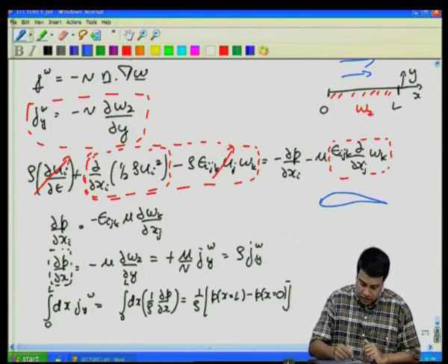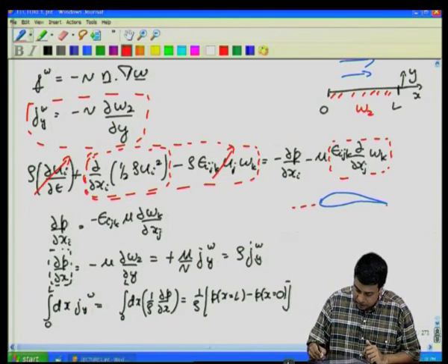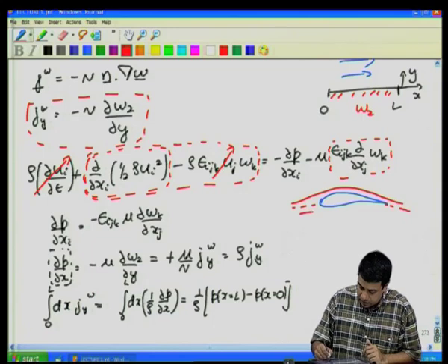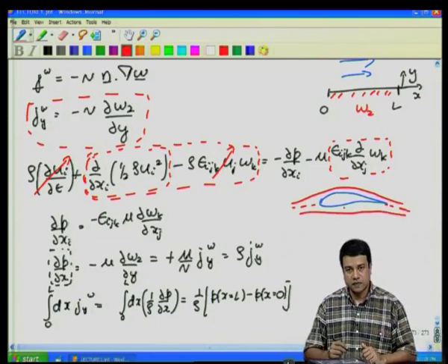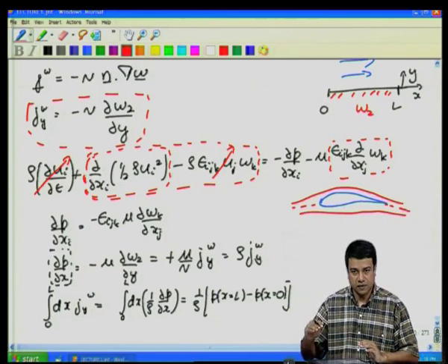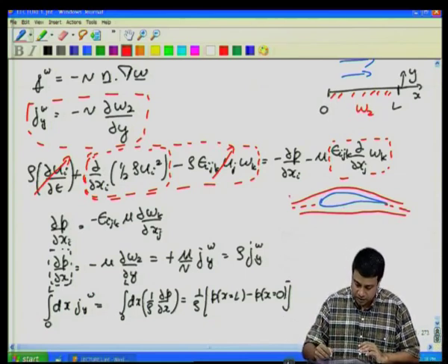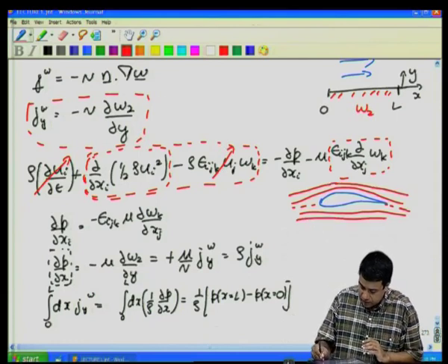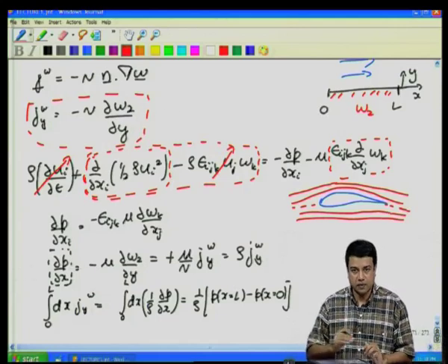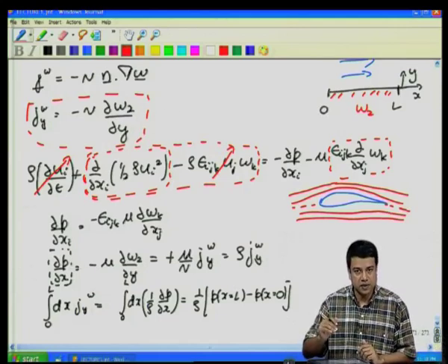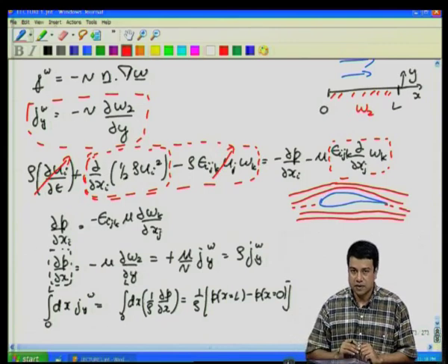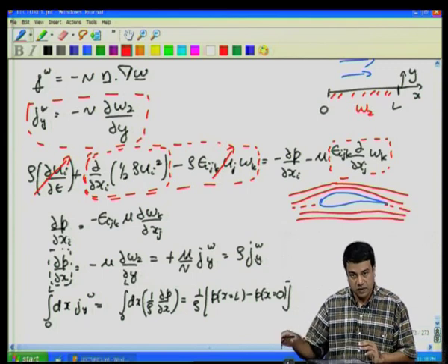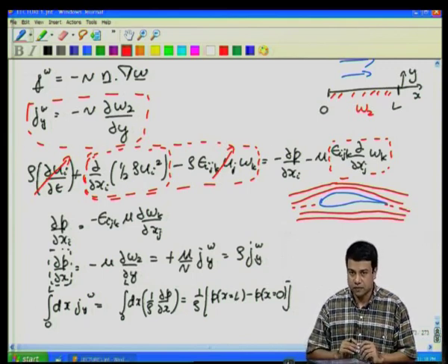As the fluid goes around this, if you look at the top surface alone, initially the streamlines are being compressed, and then they expand again, because the flow is being compressed above and below. For this case, initially the velocity increases, you have an accelerating flow, then the velocity decreases again, you have a decelerating flow.